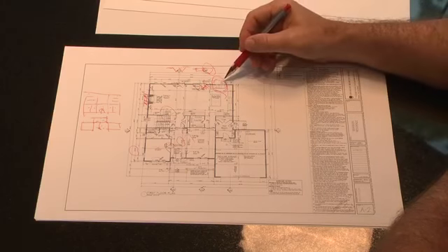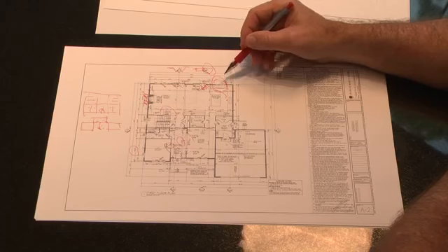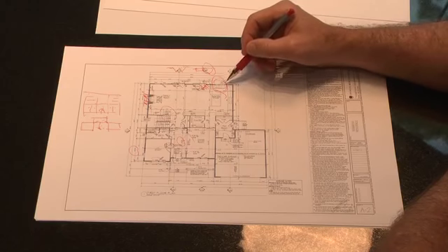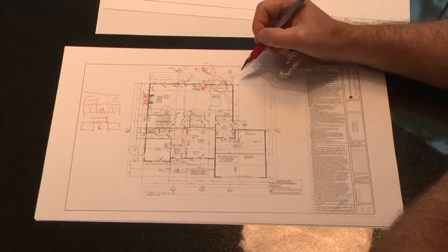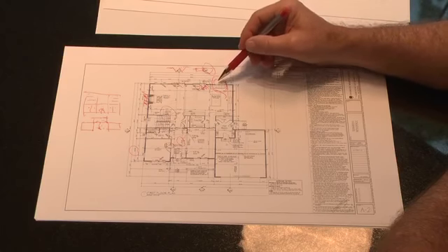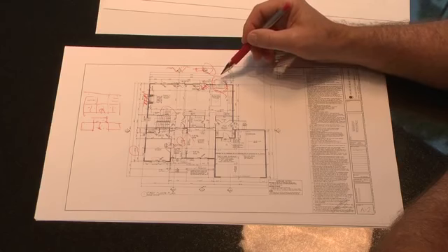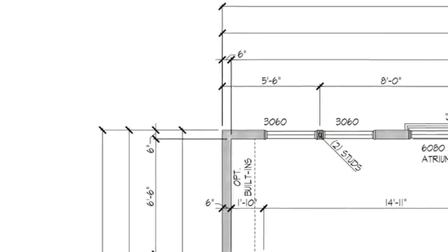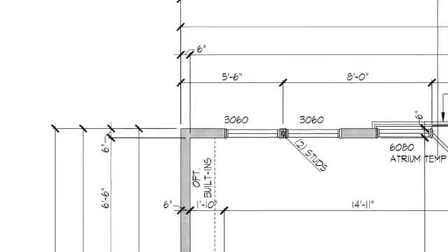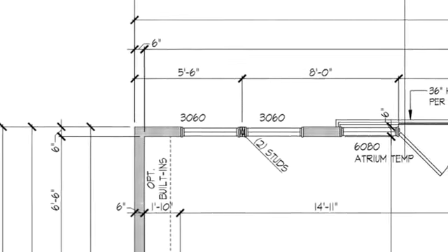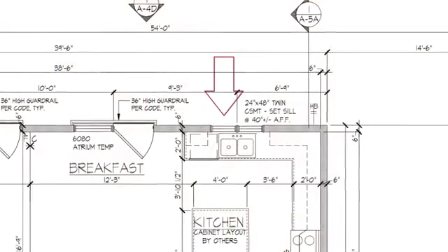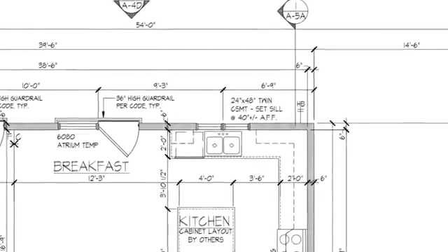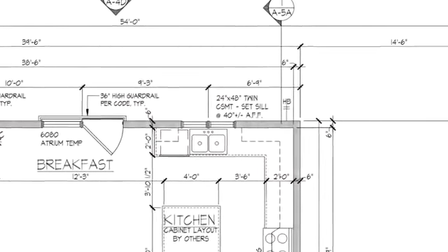So when we use casement windows, unlike double hung windows, as you may recall, we said a double hung window is measured in feet for width and height. In a casement window, it's actually measured in inches. So if we look here in the family room, this says 3 feet 0 inches wide by 6 feet 0 inches tall. This casement window is 24 inches wide by 48 inches tall. That's just the standard nomenclature in terms of allocating kitchen windows.